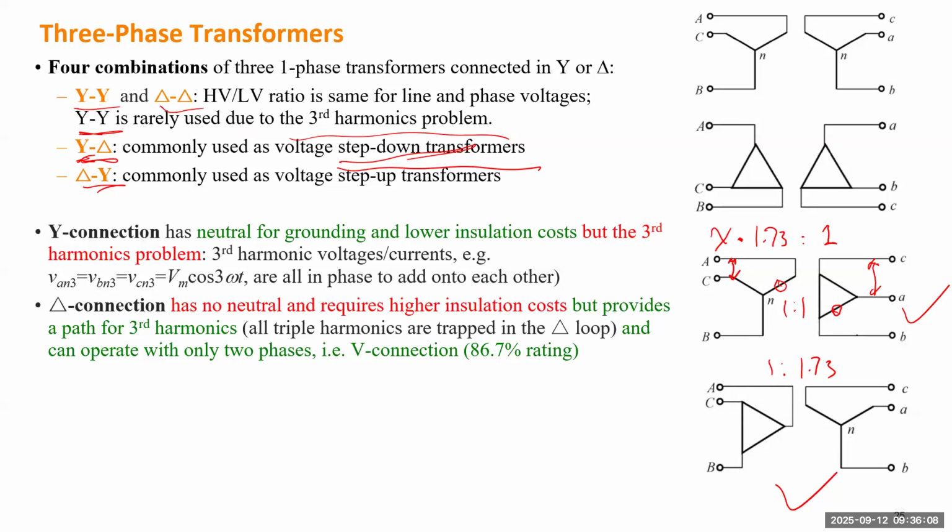The better idea is that the transformer will split the entire network into sections, depending on voltage level. In each section, it's better to have at least one Y connection. So it can be delta to Y and Y to delta. Even if you have delta to delta, it's better for the next one to use Y. So any section needs at least one Y. That gives the simplest design that still keeps the neutral wire for each section.